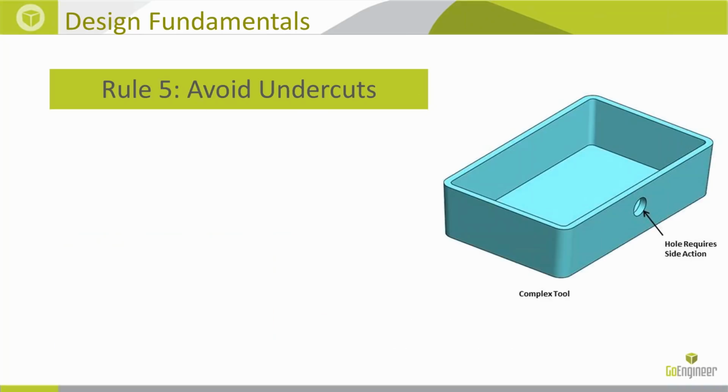Okay, so we have another rule, which is to avoid undercuts. You can't always avoid undercuts, depends on the design demands, but there are a lot of creative ways to get around undercuts, and if you can avoid them, it just reduces the cost of your part significantly.